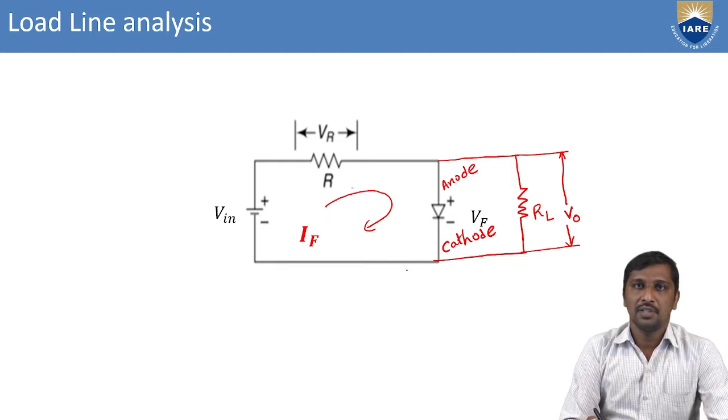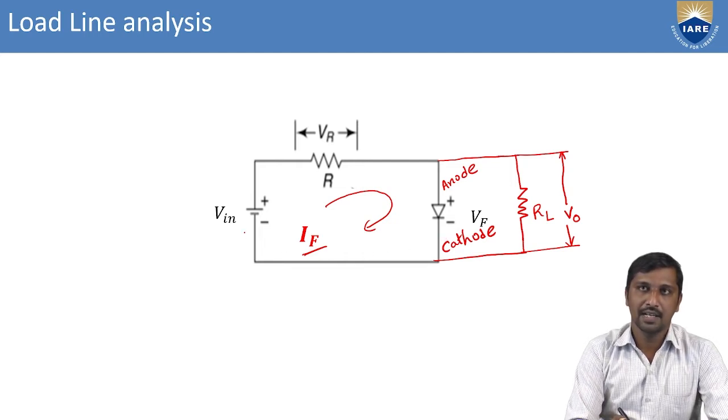According to this configuration, this circuit acts as a forward biased PN junction diode. Under this forward biased diode, the current flowing across this network is represented as the diode forward current, IF. At this applied biasing voltage, the voltage drop across this diode is represented as VF under forward bias mode.